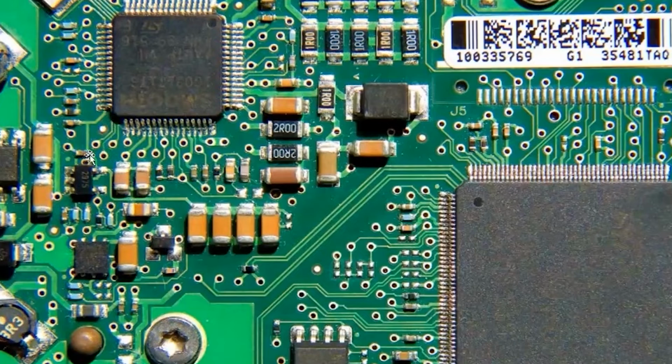Then, of course, there are other aspects of the board PCB design I didn't mention, such as mounting holes. So you can see this is where the product mounts into a board. It looks like they're tying this to... This is also ground. You can see this looks like perhaps a ground plane here, and then their mounting bolts connect in with the ground, and then this is what holds it into place.